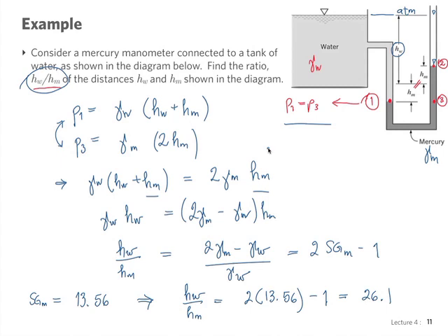Sorry, can you repeat? I couldn't hear you. Atmospheric pressure is acting on both sides equally, and basically I could include it, but it would just make my life a little bit harder because I would have to keep track of it on all of, it's acting everywhere equally. So I could just work, that's why we work with gauge pressure, because it makes it a little bit easier for the bookkeeping. I don't have to keep track of the atmospheric pressure. It's acting everywhere.